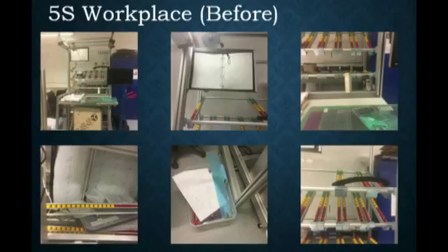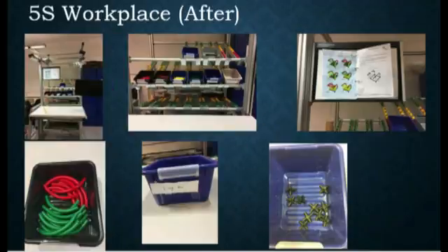These are some pictures in which you can see the condition of a workplace before implementing 5S and workplace conditions after implementing 5S. It is clear as crystal that implementing 5S will make workplace clean and organized. It is also a fact that 5S can improve flow, material, and information. If a worker doesn't waste any time on searching missing tools or materials, chances of error reduce and operations are completed as per demand and on time, hence improving or maintaining the flow.